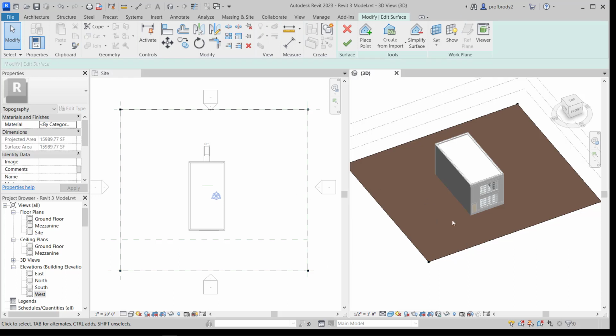The other thing is that you can add interstitial points, which kind of forces it to fold. So for example, if I want the back of the site to come up by a foot, then I just type in -1. And I'm going to add these points along the edge of the building. I find that when you're first drawing it, it's kind of easiest. And there is the nearest snap that allows you to kind of make something is angled properly, or the site is angled properly.